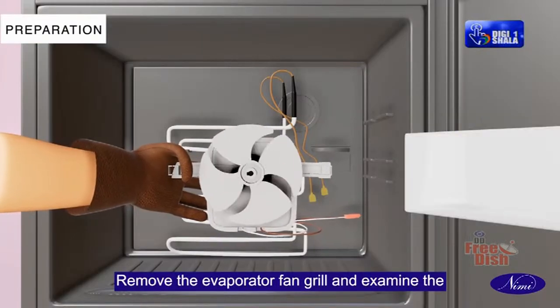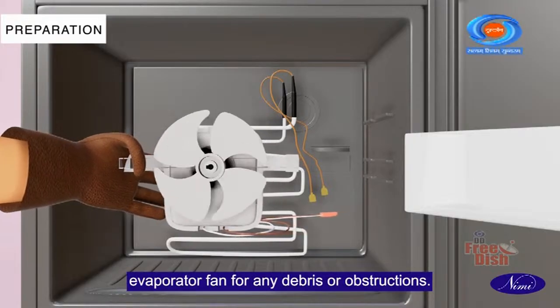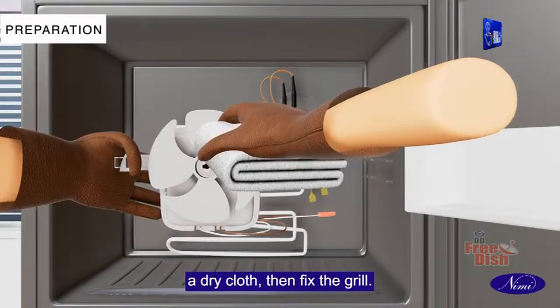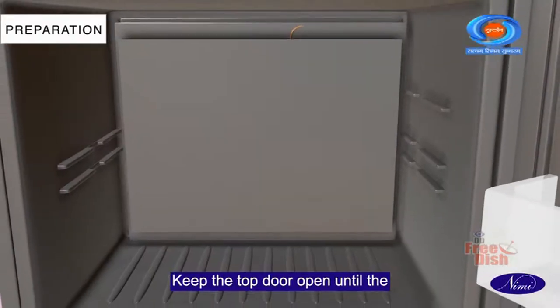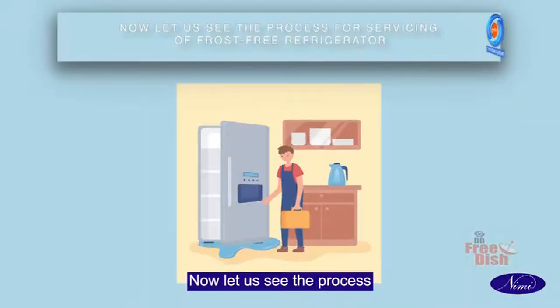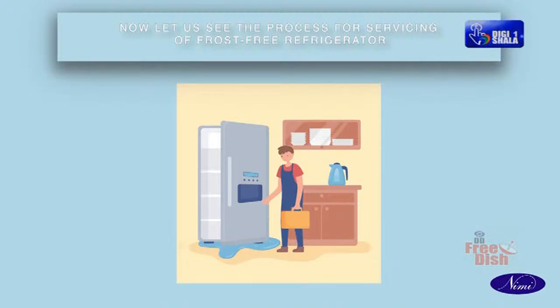Remove the evaporator fan grill and examine the evaporator fan for any debris or obstructions. Clean the fan blades and the grill with a dry cloth. Then fix the grill. Keep the top door open until the evaporator cabin becomes dry. Then close it. Now, let us see the process for servicing of frost-free refrigerator.